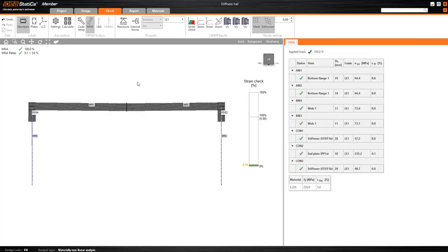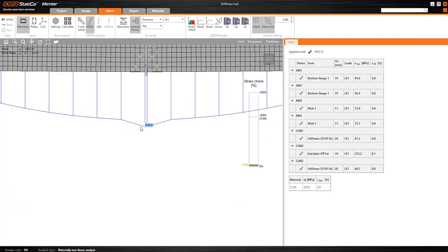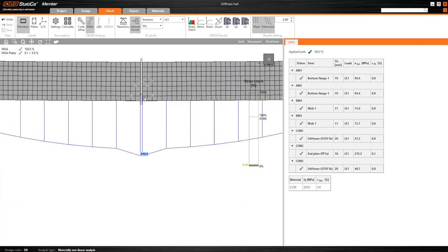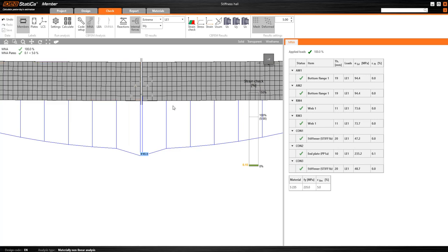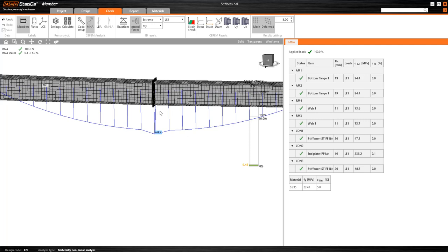So in the results, we can display the internal forces. From the trend of the internal forces, we can see that everything is correct, but right now we are interested in the numbers. So here is 70.5 and 49.4 kilonewton meter. You can see here is some drop close to the connection part. So this is our internal forces, mainly the bending moments.